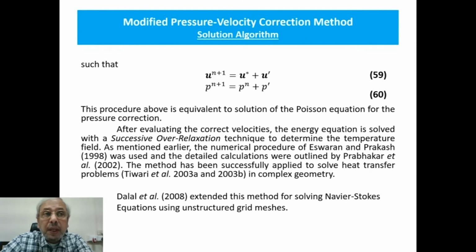Now, for more complex geometries, sometimes it is needed to adopt unstructured grids, because unstructured grids deploy, instead of hexahedrals, tetrahedrals, and these tetrahedrons can capture the tortuous geometry, the tortuosity, more accurately than hexahedrons.